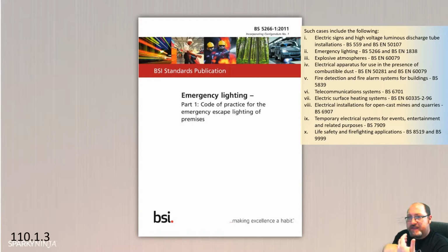There's also selectivity requirements with numbers of RCDs needed at different positions within the ICUs and the other terminology that they have in BS7909. So there's a tighter level of control and a much tighter level of certification, and there's dedicated BS7909 certification. It's not BS7671 certification.